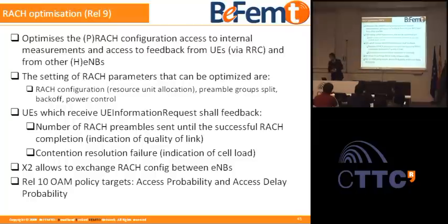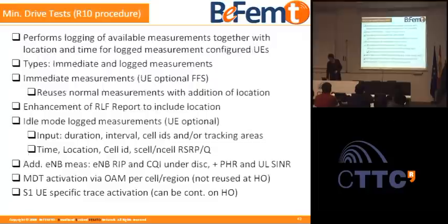Also, the radio access channel is configured using some parameters in the downlink. The base station is sending some parameters in the downlink of how your RACH should behave. It will tell you how much power you should transmit at, what your retransmission schemes are, etc. So all in all, the radio access channel, because it's a hello channel, where you're saying hello, how you doing, it's important to optimize it because it allows you to balance your network. And in release 10, release 9, they've started working very strongly on that one.